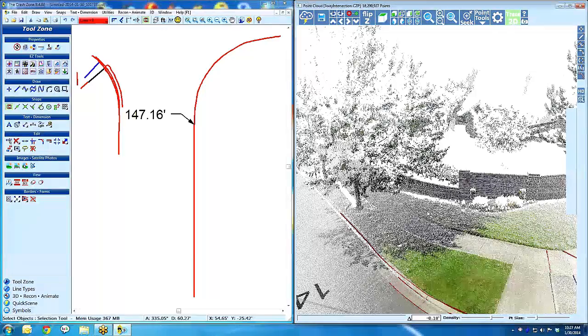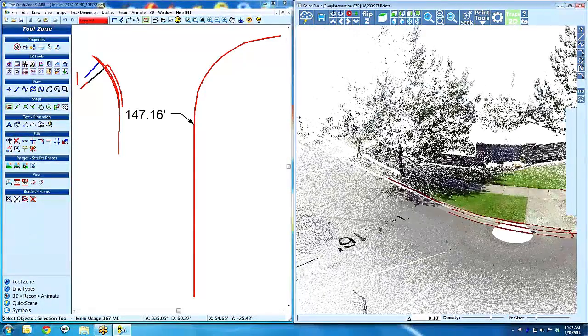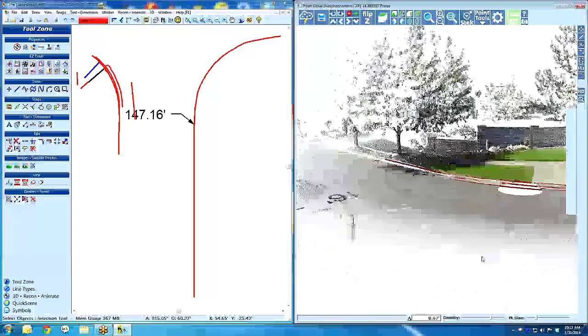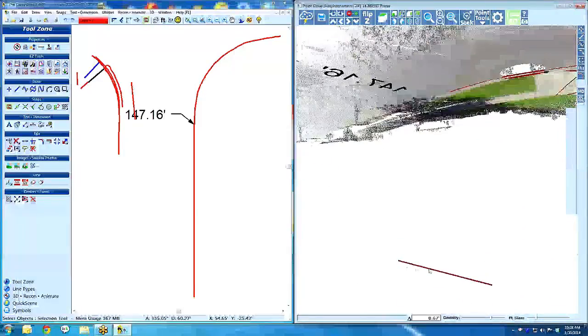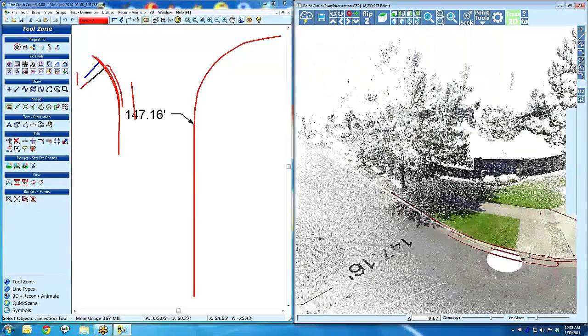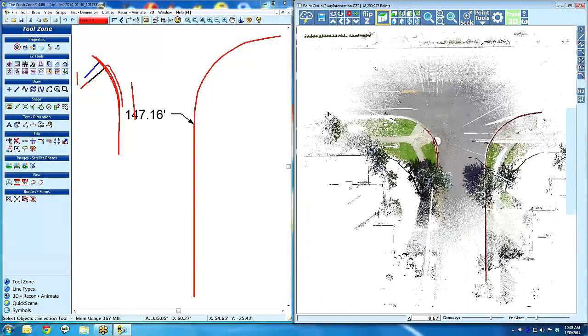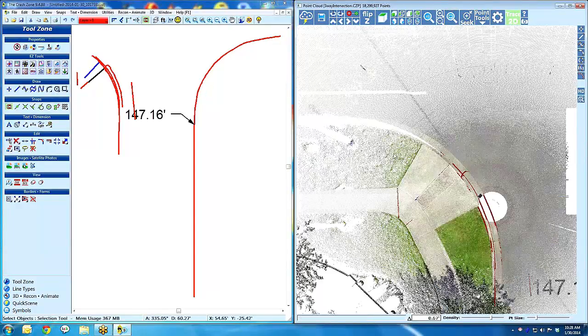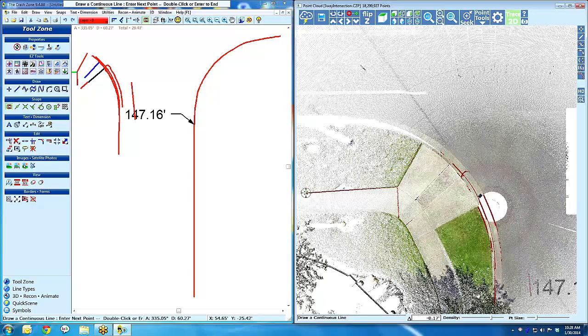And what happens is no matter where you click in the cloud, if I draw a line from here to here, it does snap to these points, but it goes all the way to the 0 level. It doesn't make a bunch of 3D lines or slopes or anything. So you go into 2D trace mode, go into top-down view, maybe zoom in on an area you want to draw, and it's very easy. You're still snapping to the real world points. You're getting nice, accurate drawings.